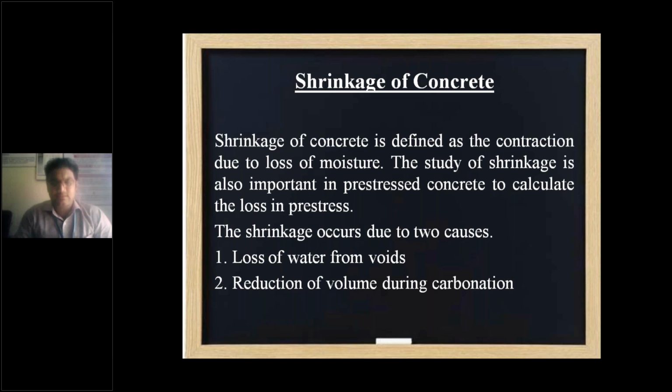So whenever you cast slabs, after casting, when you see the next day, you find cracks, hair cracks appearing here and there on the slab. Do you know what those cracks do? When you do not maintain them properly, the cracks lead to leakage. In many houses, water leaks from the slabs in due course of time. Do you know why? They were not bothered about shrinkage of concrete at the time of casting. If you do not keep shrinkage in mind while casting, the cracks will get large and allow water into it, where the biggest disadvantage is it will make the steel corrode and create a lot of dampness, and then leakages start. Understood?